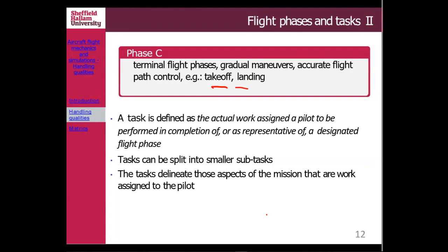It will not be fair, because a beginner pilot, for example, could not achieve the same level as an experienced pilot. So it's very important when you define the task, what tasks need to be assessed. It's very important to keep the task simple, meaning that all the test pilots involved in that flight test could do it without any big difference between one and another.